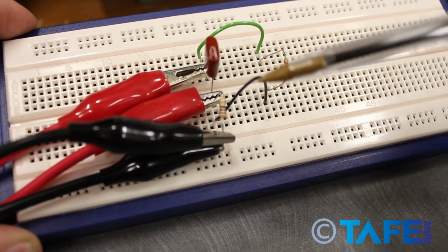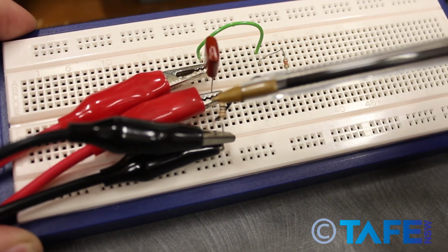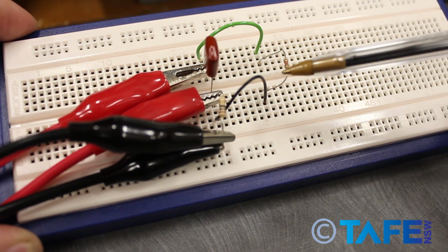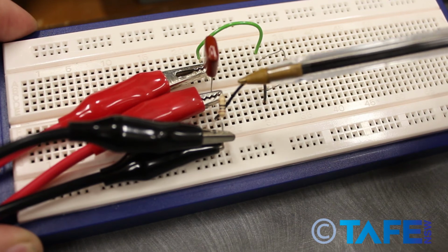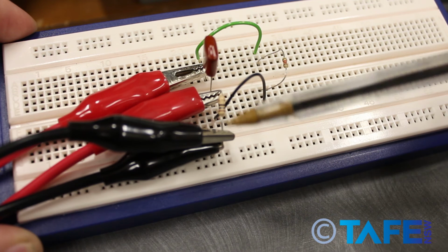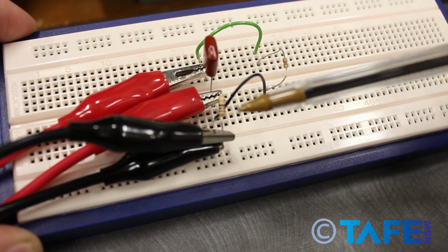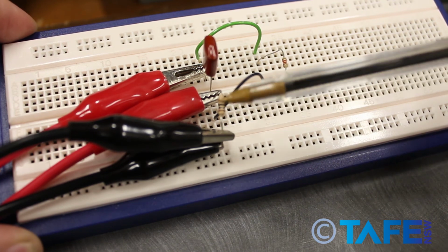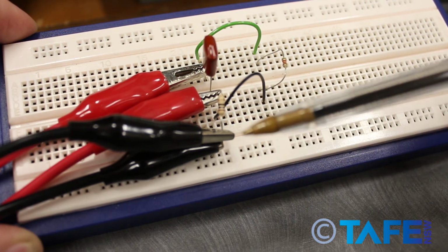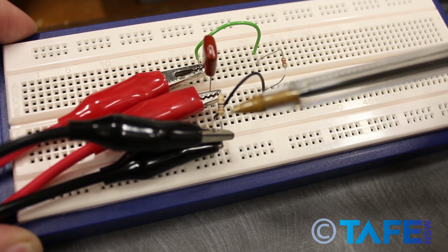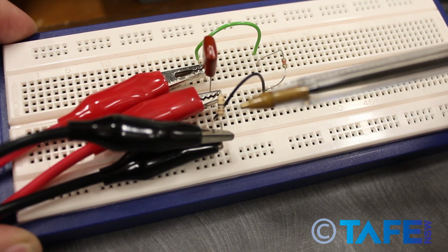I've just rewired the breadboard now, and I've only got one sensing resistor, so I've got my capacitor and my 1K resistor connected with this black wire so that they are now in parallel, and only the one sensing resistor, which I'm using on the oscilloscope, to see the voltage drop across that, which relates to the current for the circuit. We calculated that the total current should be 3.16 milliamps. Let's see what we get on the oscilloscope.